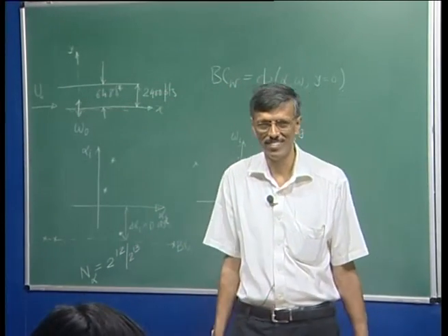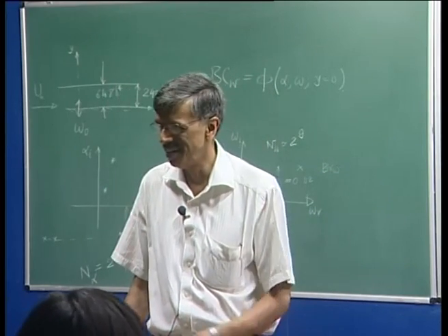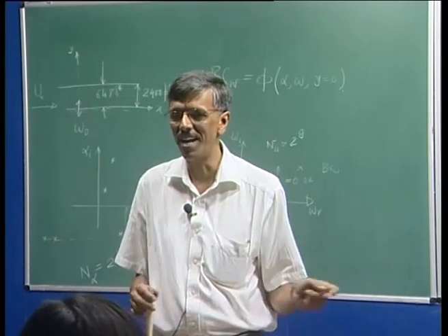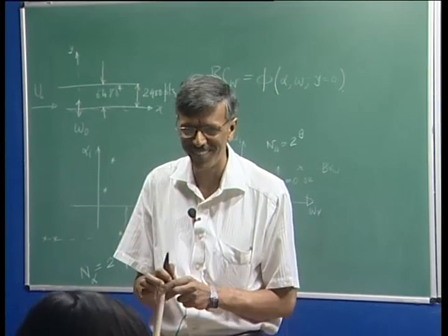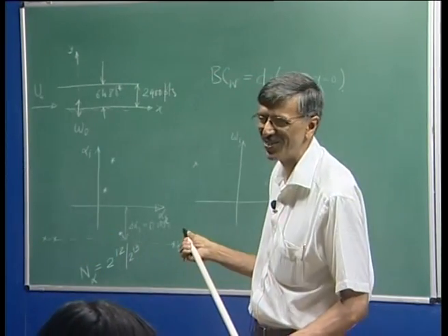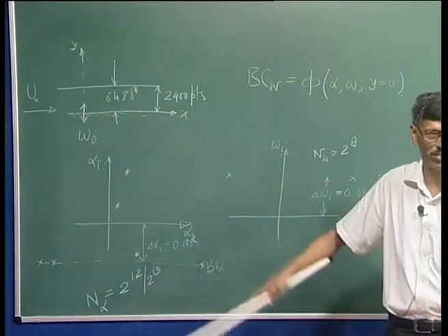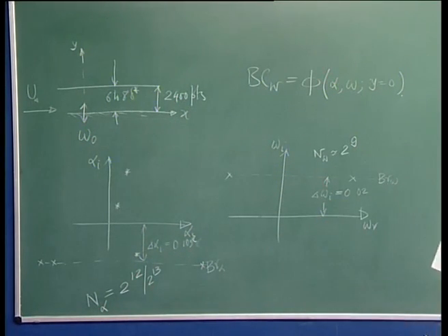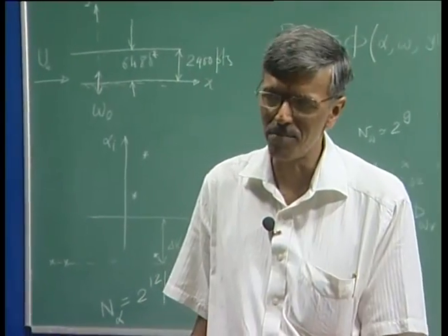within only 8 delta star. This is interesting because those of you who do CFD may have seen some publications where people say we have done a very well resolved calculation. We have taken 20 points inside the boundary layer or 100 points inside the boundary layer, and here we are talking about thousands and thousands of points, right? Because the boundary layer is about 3 delta star. So here you are looking at 1,000 points within the boundary layer. So computing equilibrium flow is one type of activity.